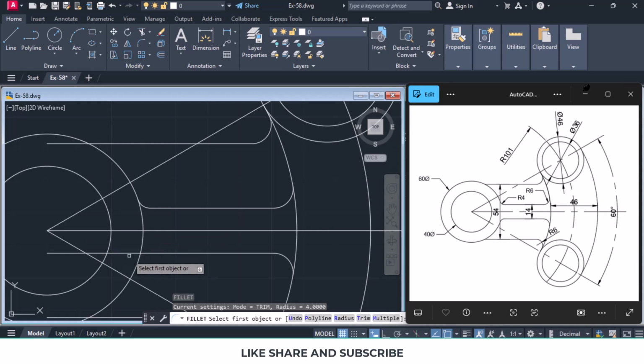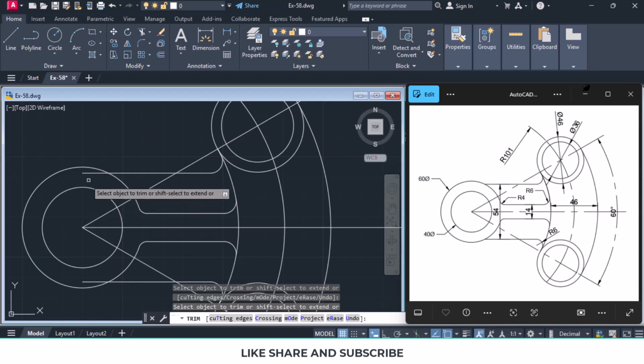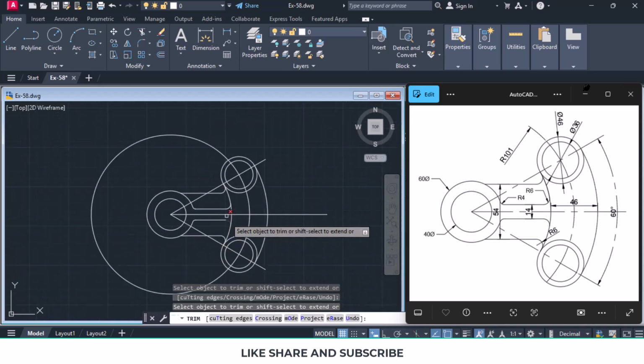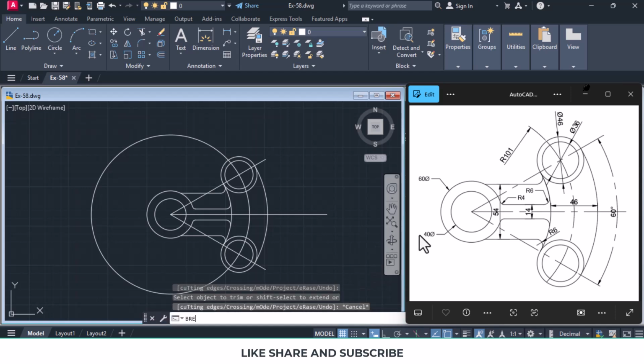Again fillet, we click on this circle and this line, and it is done. Now we don't need this middle part of the circle, TR for trim, and we don't need this, and we also don't need this. Also we don't need this extension and we don't need this extension. Now the only thing which is remaining is this outer circle, but you can see if we trim, it will trim from here. So we don't want that, so we'll type break and we'll hit enter.